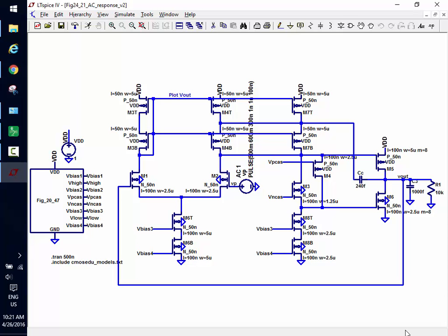If I don't give the wide output swing, 0.5 to 4.5 or 80% of VDD, then the problem's really simple. You could probably meet the specs with this topology by itself. So I need to make it a little bit more challenging for you so you feel like you're getting your money's worth. If I look at this topology, just using the parameters from table 9.2, what's the minimum output swing and why?